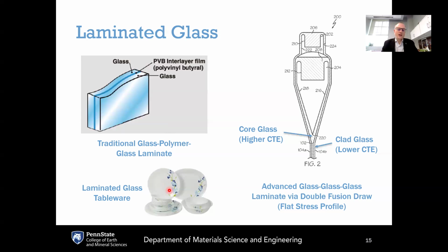And then there is a thin, clear glass that is applied as the cladding all around the plates, and that is pulled into compression, so it has a very high strength. It also has a high chemical corrosion resistance, which means that these laminated glasses will last a very long time, going through many dishwashing cycles in a dishwasher. You can also drop them and bang them, and they're actually very strong.